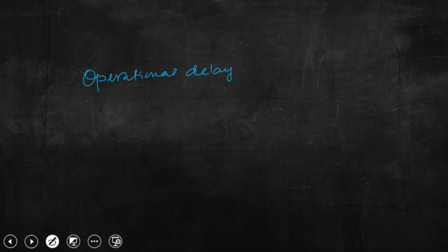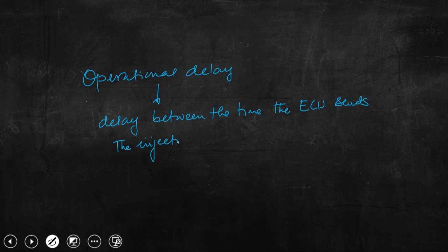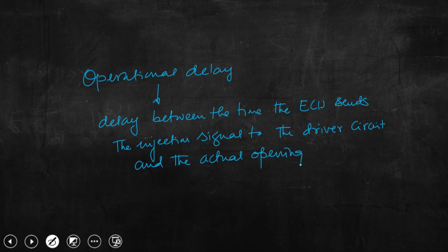Operational delay. What is this? As I told you, the delay between the time the ECU sends the injection signal to the driver circuit and the actual opening of the injector. Okay. This is the operational delay.